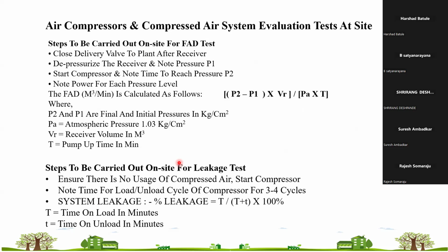Volumetric efficiency does not need the input power or any measurement of power. In volumetric efficiency, what is the displacement of the compressor? What is the work the compressor has to do? That is calculated. Free air delivery is given for your compressor, let's say 100 CFM, and it is divided by the compressor displacement.